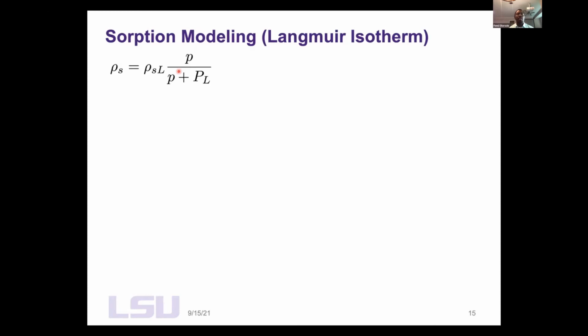And in the paper, in the book chapter we have in the advanced MRST book, we show sorption modeling, diffusion modeling, and modeling of a stress-dependent permeability. So definitely I don't have the time to go through all three, but here I'll show how we model sorption. And that means we'll go into how we modify the governing equations for compositional simulation to incorporate additional physical mechanisms that are unique to shale.